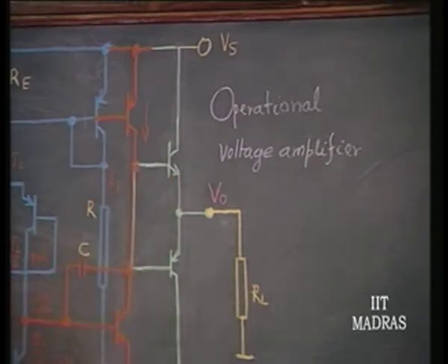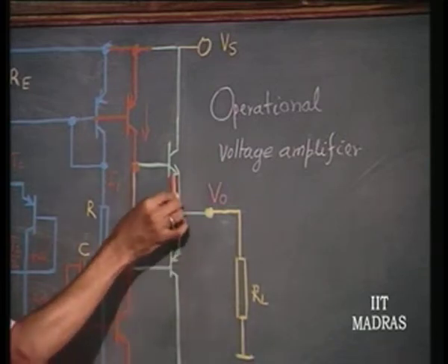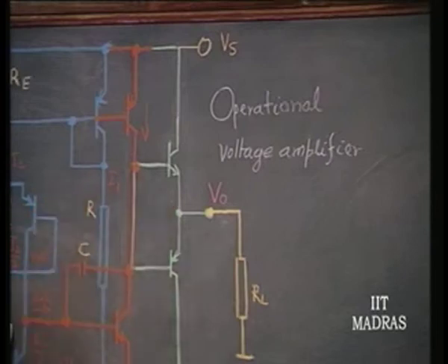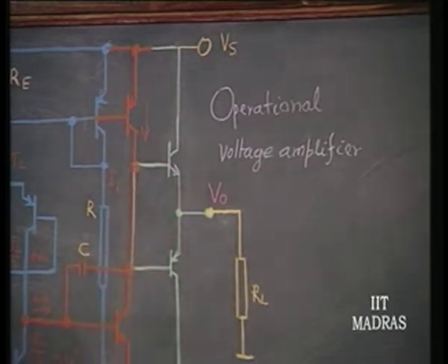Apart from that, you have to also take into account, this is an output stage, therefore, it will require short circuit protection automatically, and again the same scheme of current sensing resistors have to be put here in order to divert the drive. This we will bring in later slightly, the protection scheme, but it is exactly similar to what we had discussed for the voltage regulator. So, there will be series resistances coming in series with these emitters, and they will naturally come as additional output resistances.